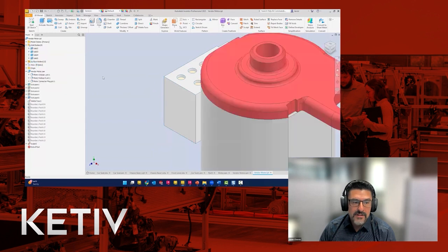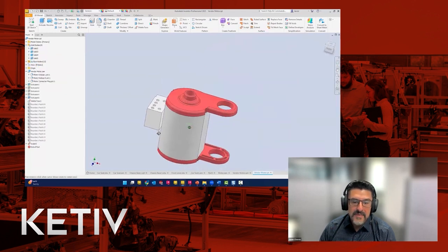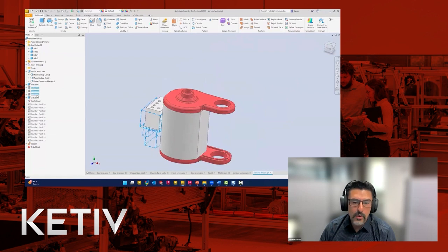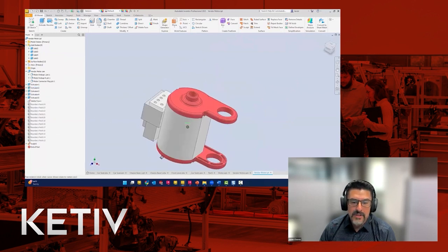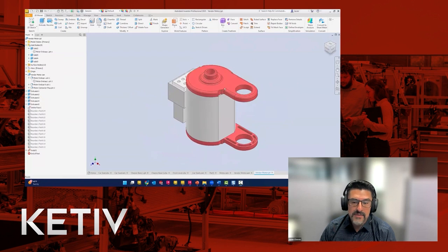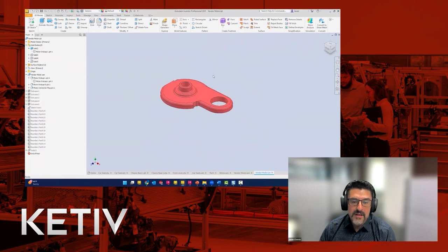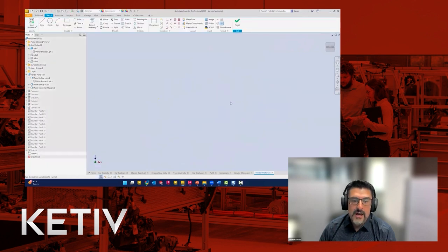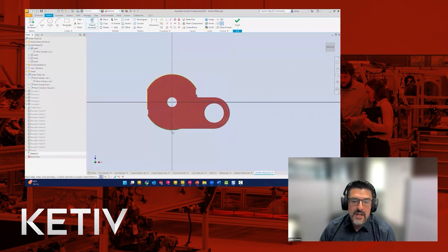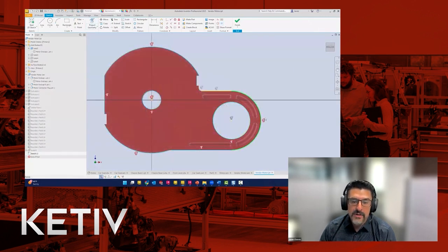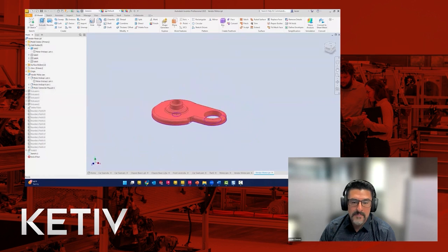And so if we start to bring things back, the only thing that's left are these red components, and we'll streamline the process for this, but that's the only thing left that we need to simplify. The two components are exactly the same, just mirror images. So we're going to focus in on one and really go through the same process of using simplification tools, sketching tools, and just common modeling tools, right? And we are borrowing from the original, so we're borrowing edges, disassociating them eventually, because that red part will go away, and we'll replace it with our own extruded version of the same thing.